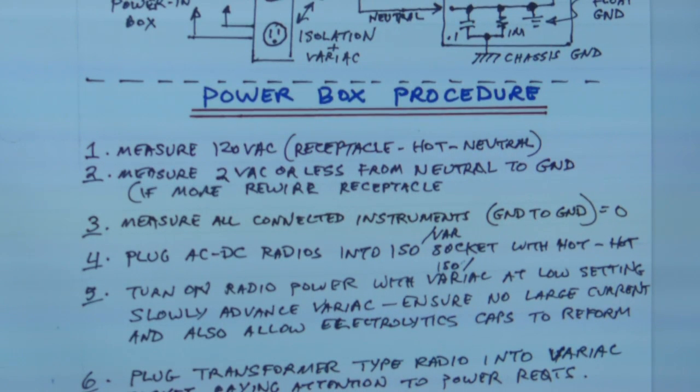If you're not, you've got some stray voltage or leakage around somewhere, and you've got to debug that. You've got to make sure you don't have that. Otherwise, when you turn on your scope, you're going to have a 60 hertz waveform with your tiny little signal being carried on the back of this huge 60 hertz waveform showing up on your scope. And that's an annoyance, and you don't want that. It just complicates the measurements that you want to take. So you've got to get rid of it. All right, so that's why that's there.